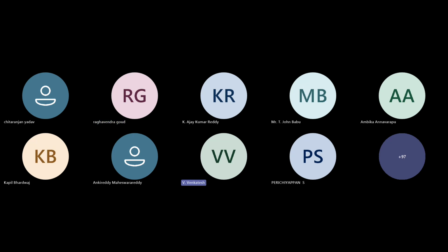If you wanted to develop a ceramic product using my setup, you have to mix ceramic powder with a binder material and print the product. It is called a green product. After sintering it at very high temperatures, you will get the required one. At the time of sintering, the binder material gets evaporated, so you will get the final product with ceramic material.